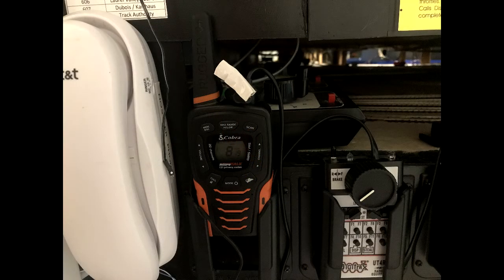I use a Dingotel USB audio adapter to make the connection between the FRS radio and the computer. The Dingotel adapter switches the microphone and audio output functions from the radio into the computer, allowing the mic function of the computer to access the speaker function of the radio and vice versa. The FRS radio is set to the Vox function and operates in that mode in order to transmit across the radio network and communicate with the other remote operators on Zoom.